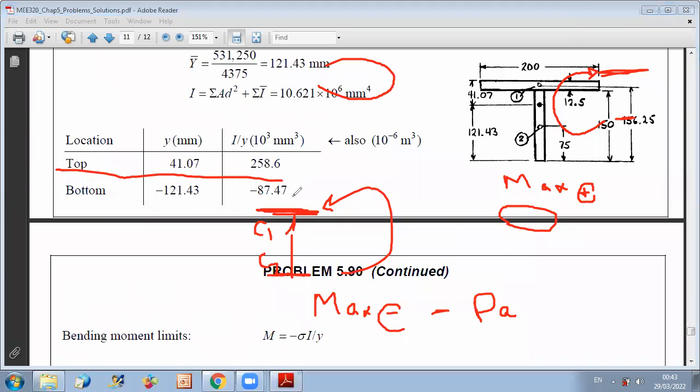Of course, you can say, since I'm designing to find the critical value of moment, I should take the minimum between the different critical cases. You remember when we have a maximum bending moment to not reach compression allowable value, or maximum bending moment to not reach tension allowable value. When I do the calculation, I select the smallest at the end.